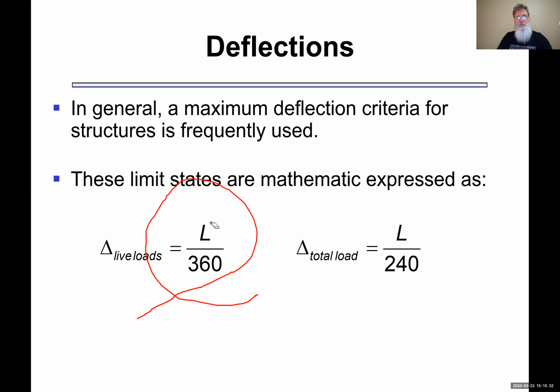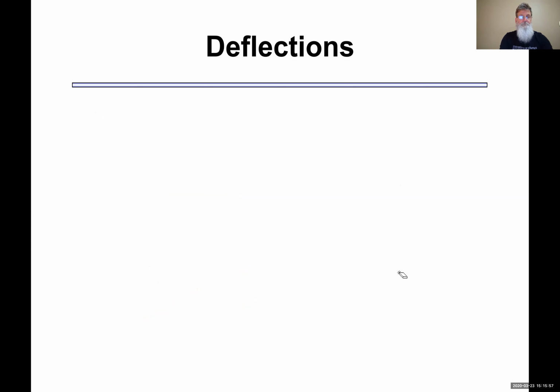So if you look at this, L maybe 10 feet tall, that would be 120 inches, 120 inches divided. You're talking about half an inch per floor times 100 floors. You can do the math. You can see there's a pretty small amount of movement that's required under those. So displacements are quite interesting, a little more challenging to compute, but very, very important to design.